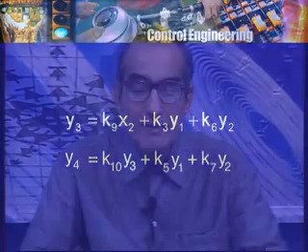So, for each one of the 4 nodes y1, y2, y3, y4, we have an equation, and there are the 2 input nodes x1 and x2 for which we have no equation. They are input nodes, there are no incoming arrows, so there is no equation. And now we would like to obtain expressions for the nodes other than the input nodes, which means in this case y1, y2, y3 and y4, the node signals, in terms of the input node signals x1 and x2.